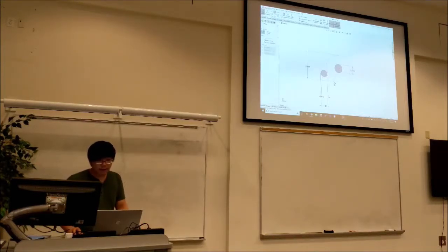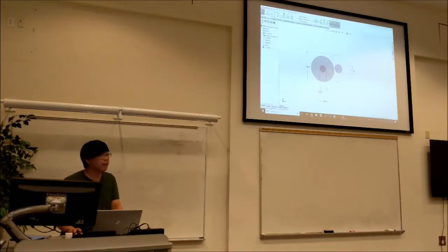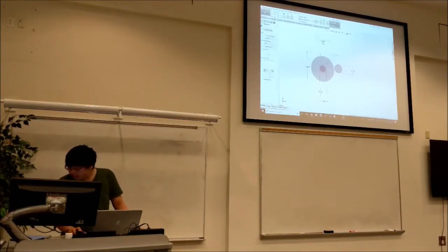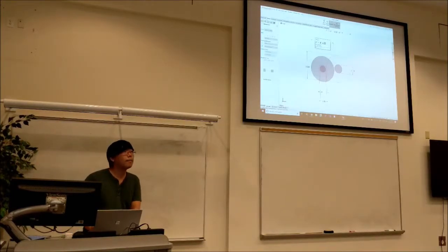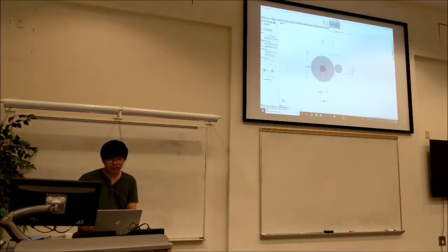Now we have another gear, right? So this gear is part of the first stage, and this is where the 775 Pros are going to be connected. So if we dimension this, that is an 80 tooth gear, so we're going to do 80, but because it's connected to the 775 Pro, we need to do 32 DP. So it's 80 divided by 32 plus 0.003. And then because it's a gear, it's not actually part of the final part, we can make it construction geometry again.